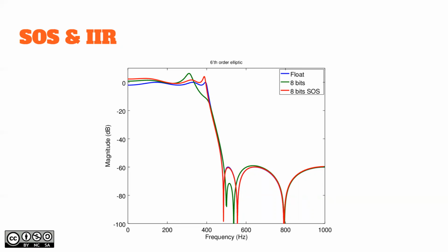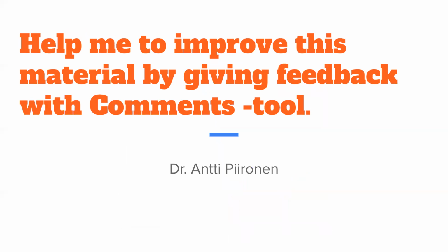But even if it doesn't, it usually moves the angle of those poles, and then you are moving the ripple to a different place, meaning that it degrades the passband performance a lot, which is actually the worst that can happen.